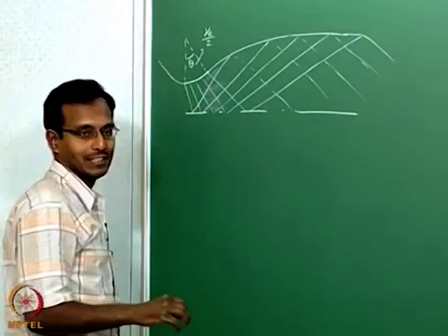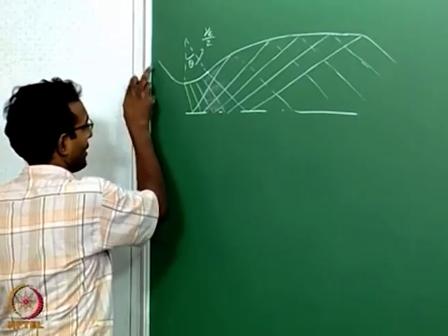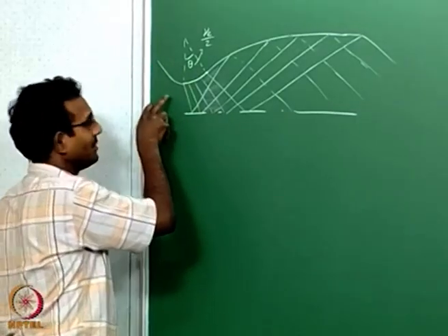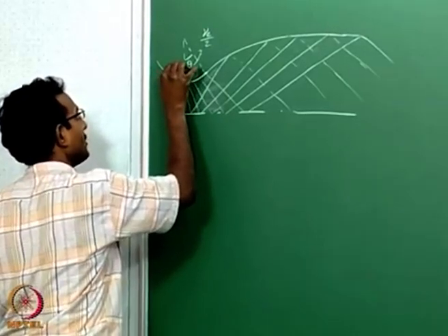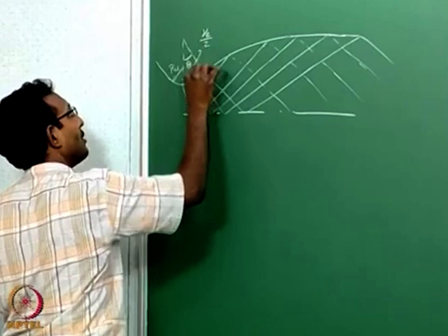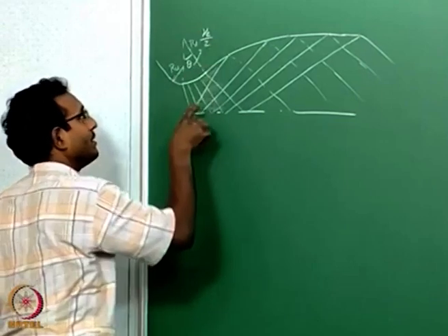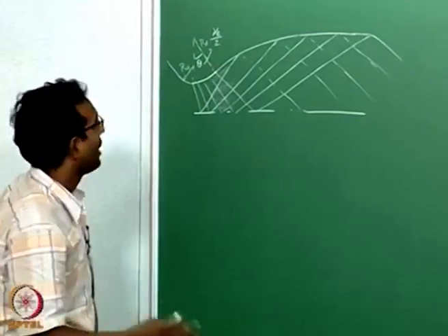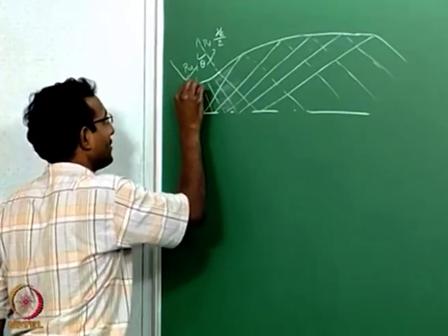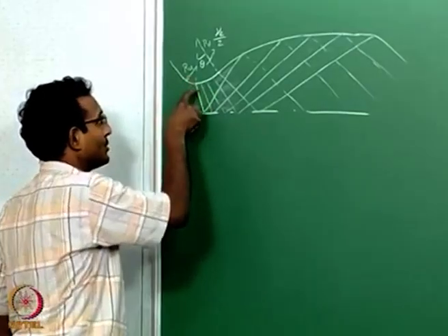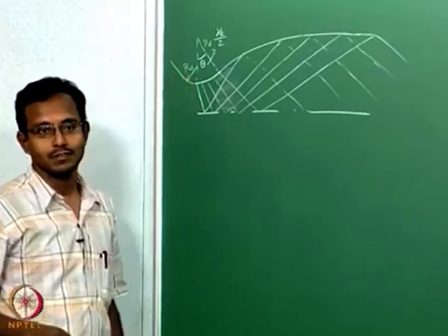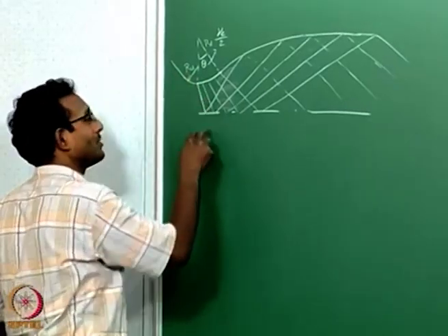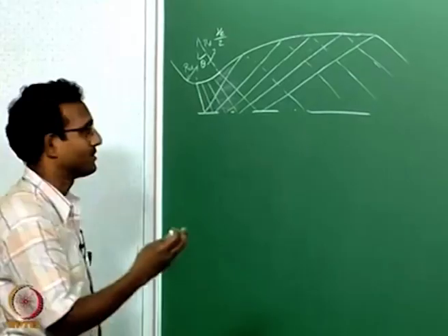When we are designing a nozzle, they will just put typically maximum angle of convergence as 45 degrees, and then it will have a small radius here. We talked about this R upstream, and this one we called as R downstream. We can pick R downstream to be anything. R upstream decides the initial line here, very first line with a whole bunch of points on that is given by this R upstream. Okay, we will talk a little more about this after we see some pictures.